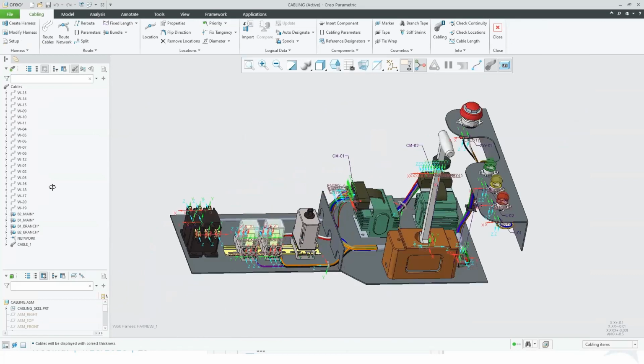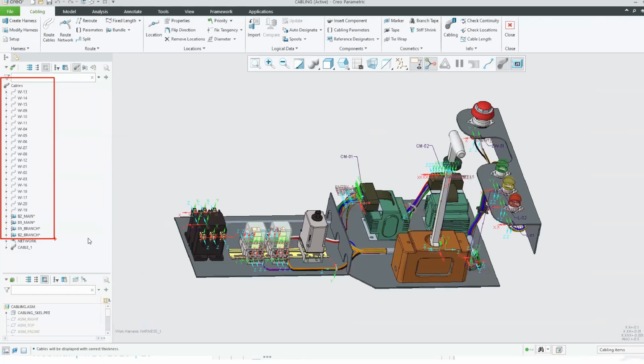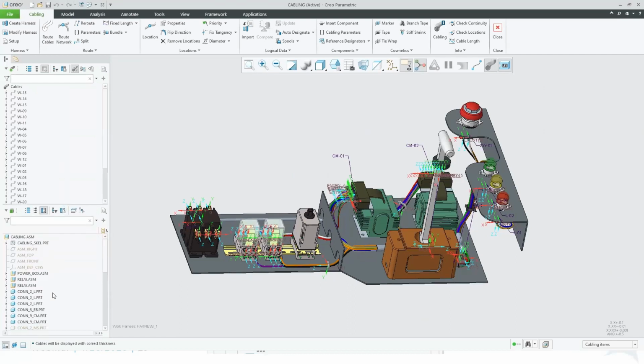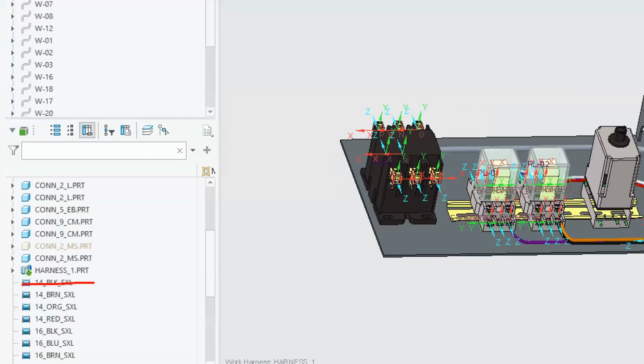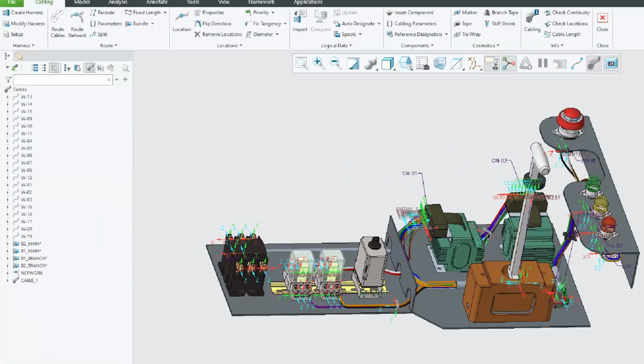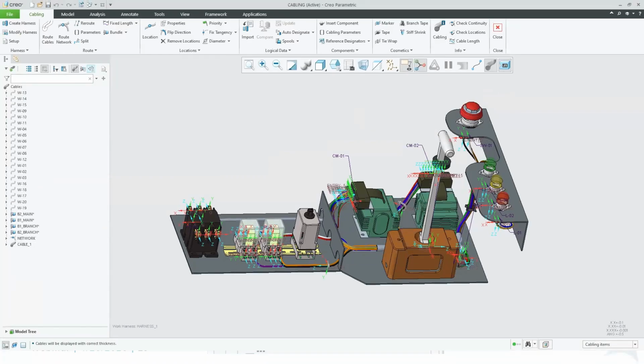Did you notice one thing in Creo 10? Immediately when I open up a cabling or enter cabling mode, I get a split tree now. That's really nice, I think. Before, all the way in Creo 9, the harness part was still there, and everything was in here under the harness. I like how I can just minimize that model tree, and there are three options now: your cable tree, your bundle tree, and your connectivity tree, right?